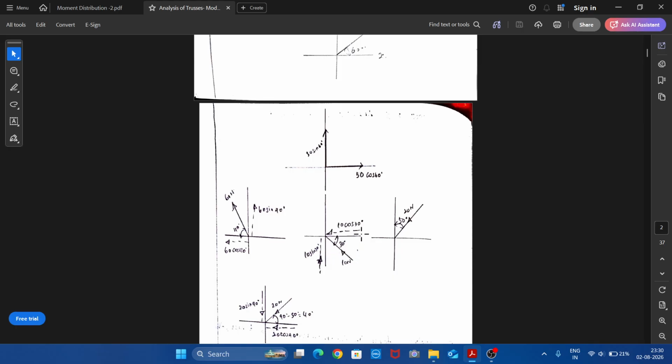Say if I simply bring this force here, what will happen? So the arrowhead moves, what's the direction of the arrowhead? It will move towards left, therefore minus. And if I resolve it vertically, the arrowhead will be pointed upward. So it will be plus 10 sine 30.